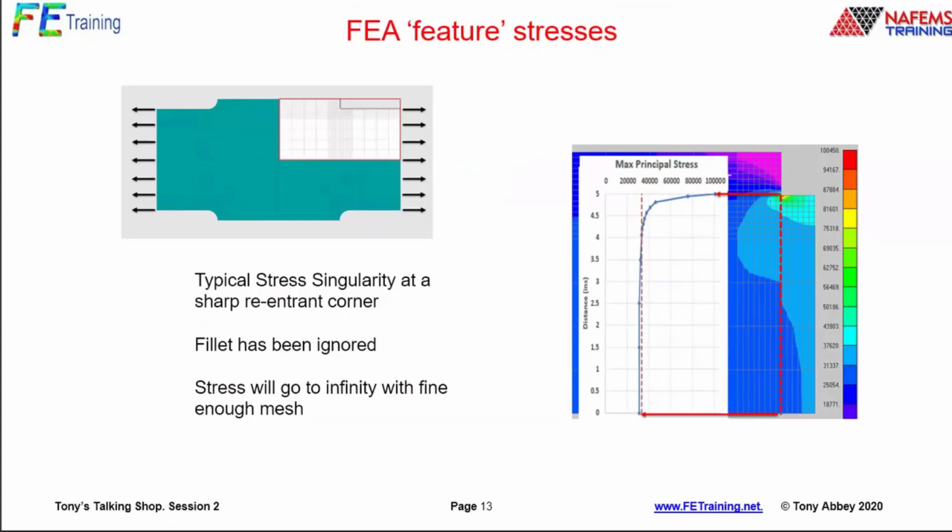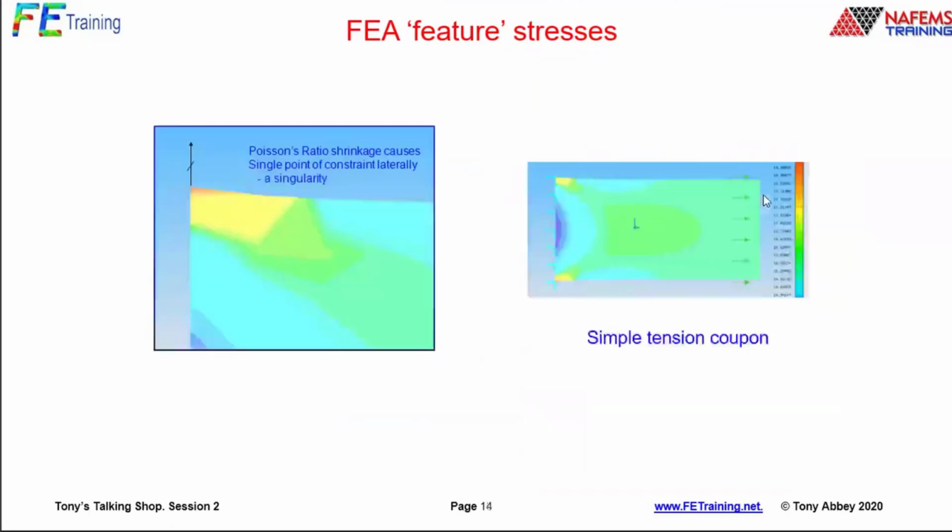So if I've got a feature like that, I have seen people sometimes quietly move another part of the structure in front. That's a little bit of a gray area. Shouldn't really be doing that. You should be exposing that and saying, okay, it's there. It's an FEA feature. Trust me, I'm an engineer. It's not an area of importance, and I'm going to allow it in there. But there's a justification. There's an explanation in the FEA model. So maybe that's why we get stresses, say, 3 or 4 times yield, but we explain why they're there.